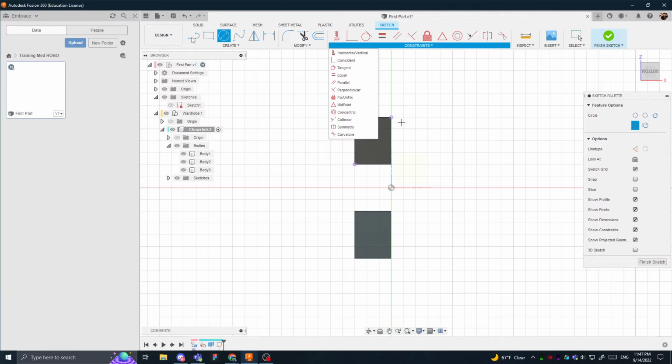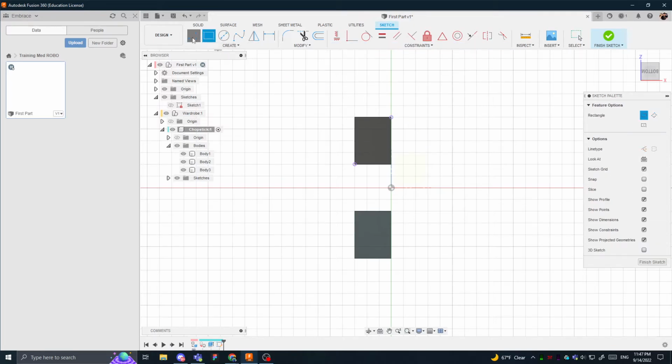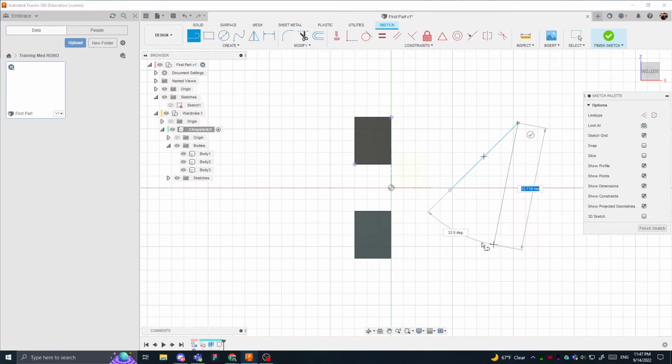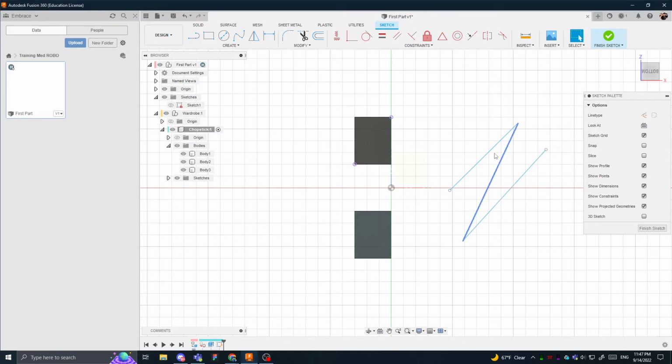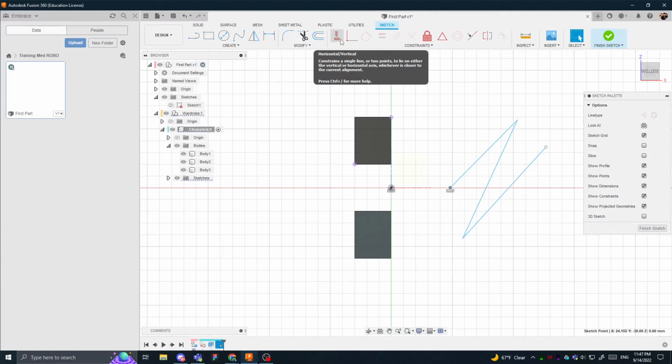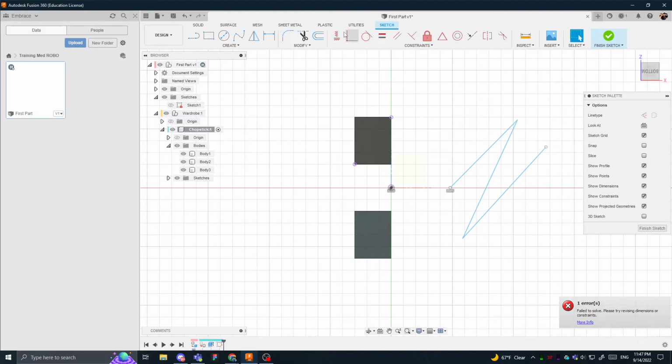For example, if I made a line, it's not parallel, and that's not parallel at all. Let's say I wanted this line to always stay at the same height as that one. I know it's horizontal, so now I can't move up and down. So just knowing that these symbols represent certain things will be very useful. Coincident means that they have to hit, like a point has to always stay touching one line. So right here, this is coincident.